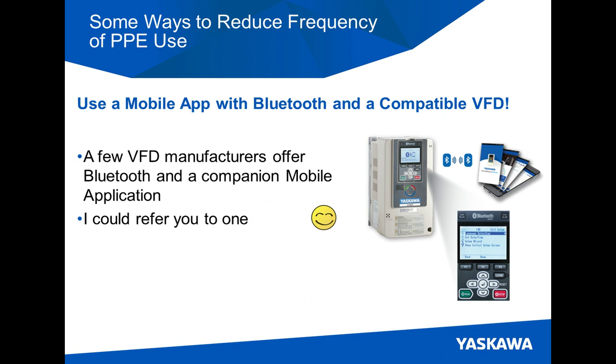If you do open a cabinet door, you're going to have to wear PPE, like for routine maintenance, for cleaning the fans or checking electrical connections, or even troubleshooting failed electrical circuits or for fuse replacement. So like I said, there are some benefits, but you can't completely negate the need to get at the hardware of the drive in some instances.